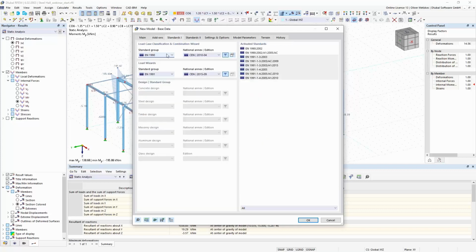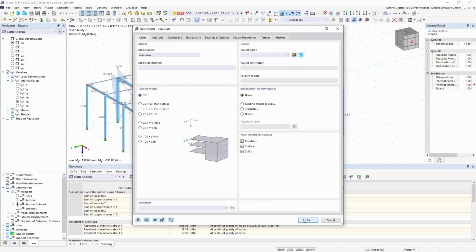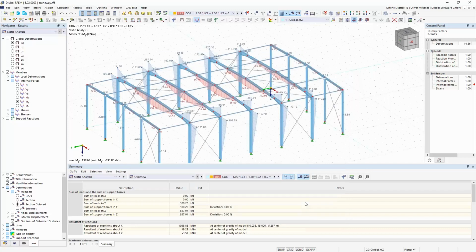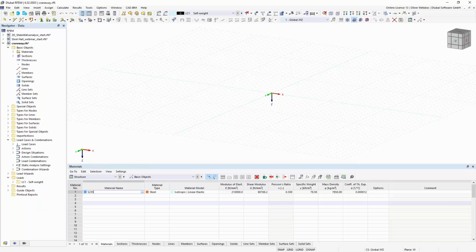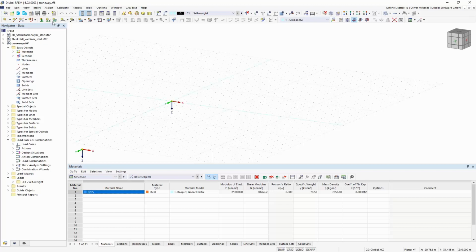And as I want to calculate a craneway girder now, I also changed the load case classification for the craneways. Okay. So in this example, I don't want to deal with all the necessary design checks for the craneway girders. So we don't have them implemented yet in RFEM 6, so no fatigue design checks, for example, and we also don't have this moving load situation, so that will be implemented later. But now I only want to show this example because then we can look at all the details for the calculation with the warping torsion add-on, because we will get these torsional moments inside our craneway girder. Okay, it would be a very easy example for the beginning.